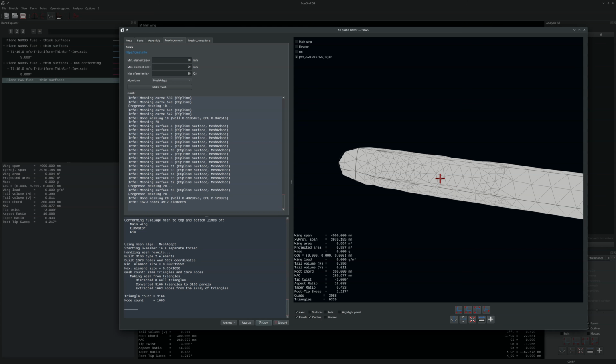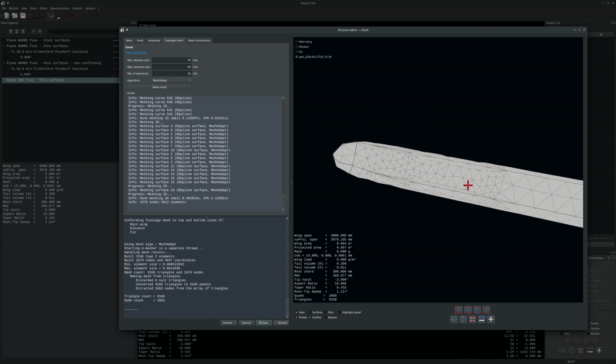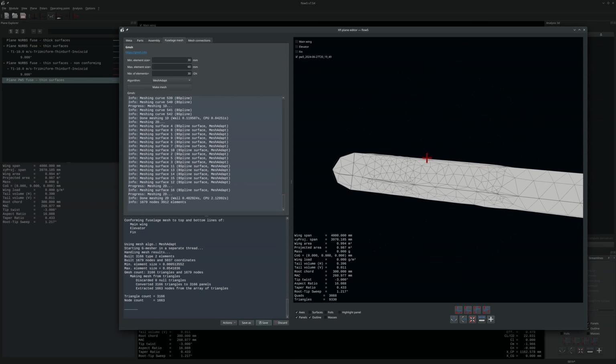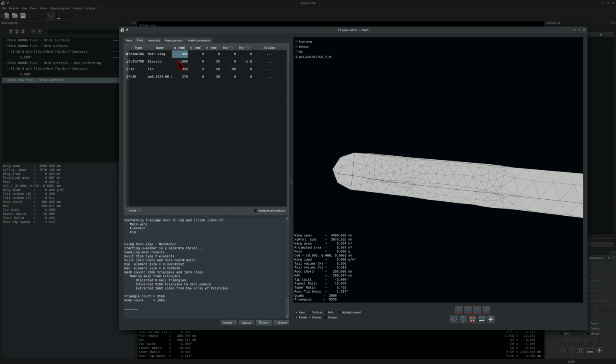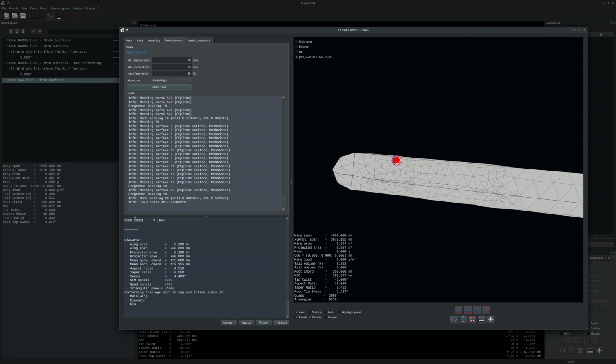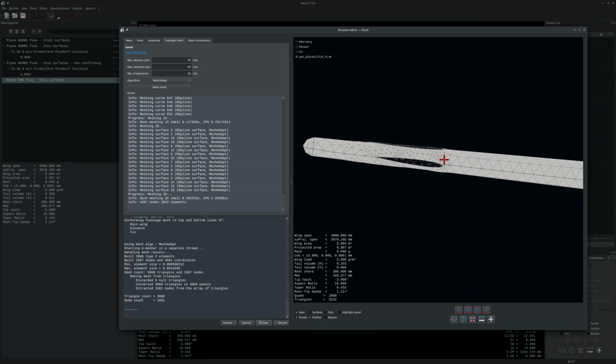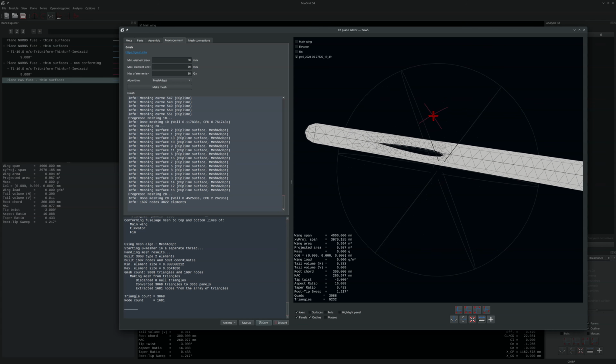What my trial and error so far seems to show is that it's linked either to this edge in the split line and the top one too here, or rather to the small cross section, because if I move these parts forward, let's say by 100 millimeters or 150 millimeters, 200 and 200, 1200 and 1200, and run the meshing operation again, let's see what happens. Sorry. Well, yep, the meshing operation went much better.